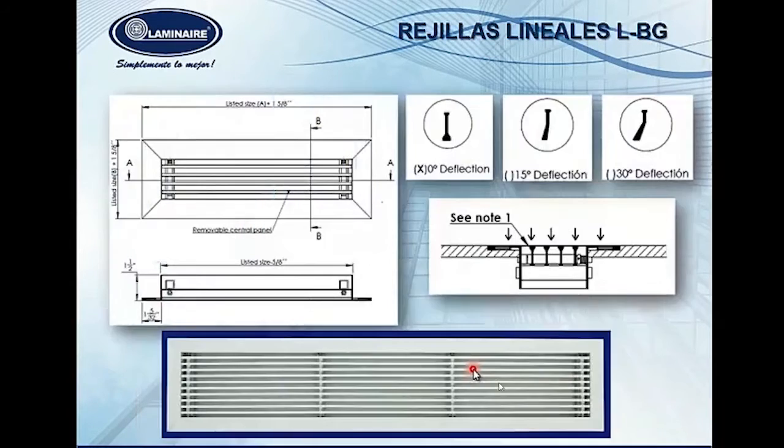So right here we can see the linear grids: 0 degrees deflection, 15 degrees deflection, 30 degrees deflection. These angles are totally fixed. It means that when the selection is done, if it's 0 degrees deflection, it's always going to be 0; if 15, it's always 15. One of the applications for this kind of grid is the floor application, which could be done for supplying air or microclimates. This grid or screen allows a moderate traffic over it.